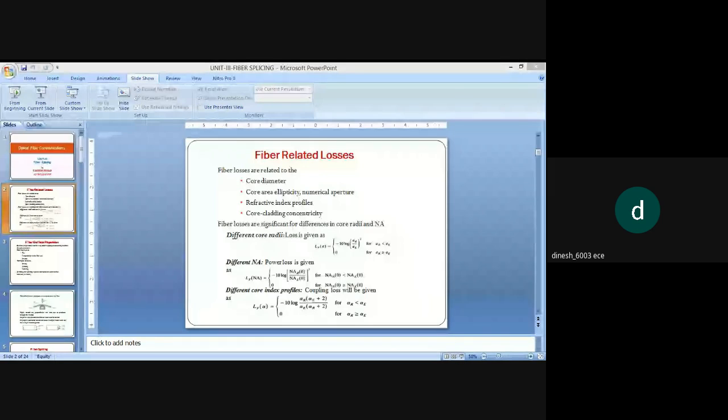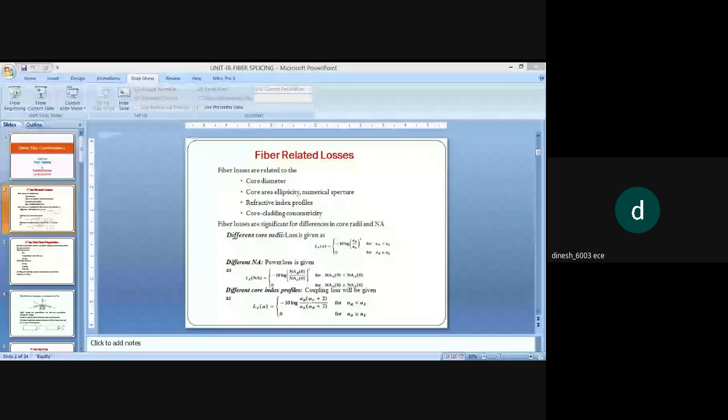Then we have an electric arc welder, or a laser fusion welder, which will press these together, and here a thermal bonding of the two fibers that are to be spliced takes place. So the chemical melting sometimes may produce a weaker splice, and it may be required to produce very low splice loss.